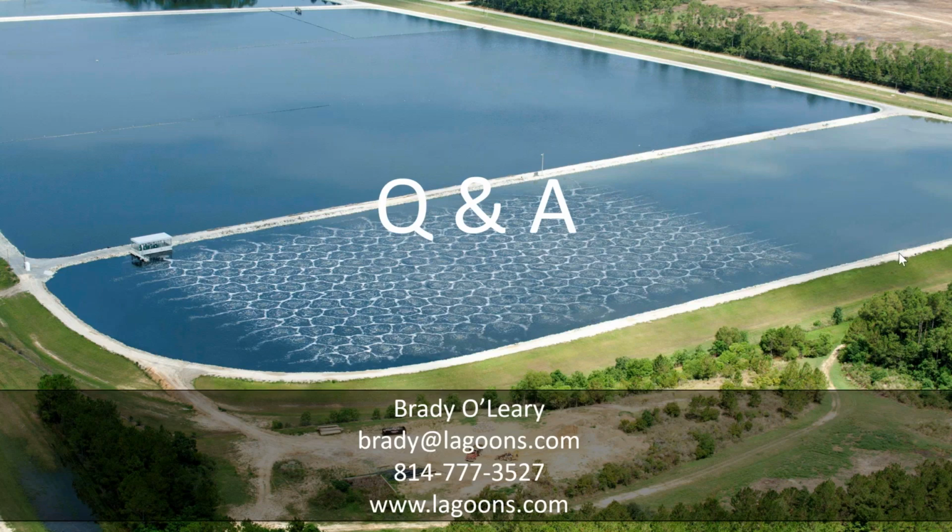Would it be advantageous to aerate the lagoon intermittently? Potentially, if you're trying to do some kind of sequencing reactor where you're trying to get additional phosphorus removal, but in general, what we see is tapered aeration, where you start with a lot of aeration up front, where you have the majority of your demand, and you slowly decrease it thereafter. So I don't think doing it intermittently would be very effective, unless, of course, you're trying to put air on the back end of your system. Maybe you have an effluent requirement of high DO. Maybe you're running your lagoons at 2 or 3 DO, and your permit says you've got to come out at 5. Some people will put aeration at the tail end to boost the air at that point.